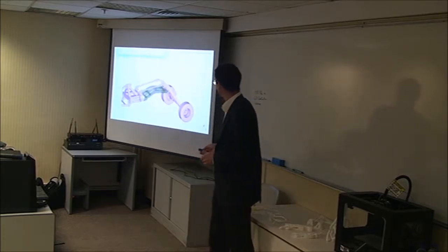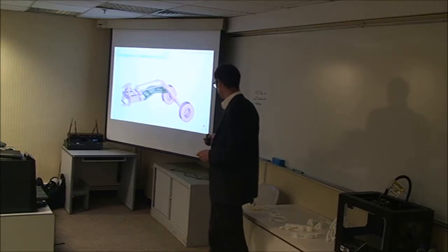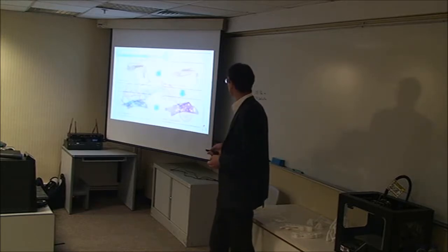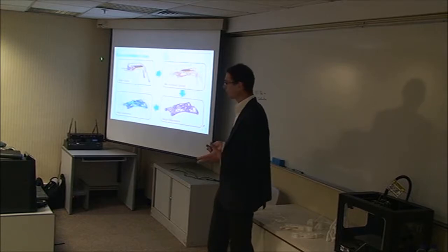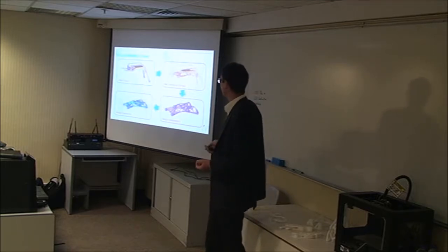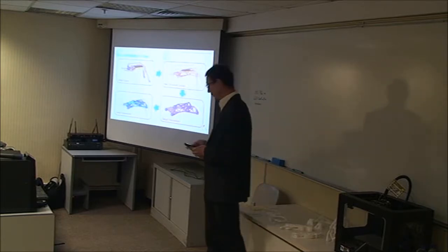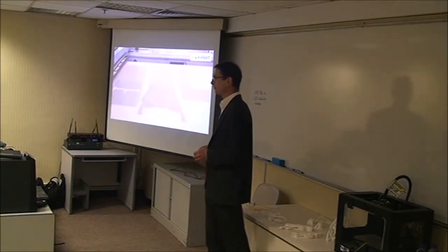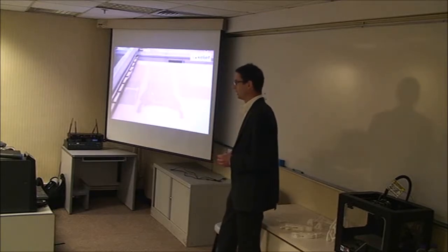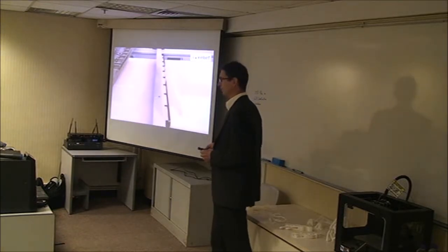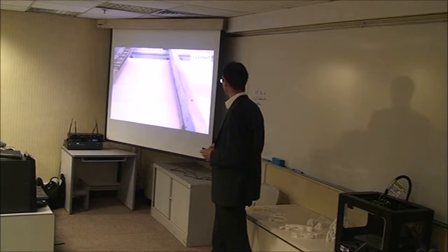exclusively for that project. You do an MBD simulation, a motion simulation. You get the loads which are applied to the part. Then you define the same steps, design space. You run the optimization. You get the design. You interpret it with PolyNURBS, and you recheck if it will work. And then you go into printing, and that is the tool printing process of the later casted parts. It is actually sand which was used for these printed kernels.